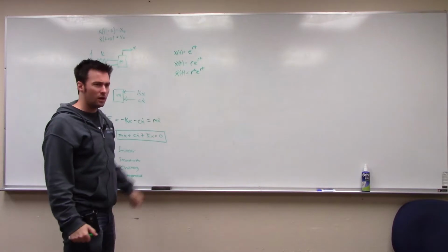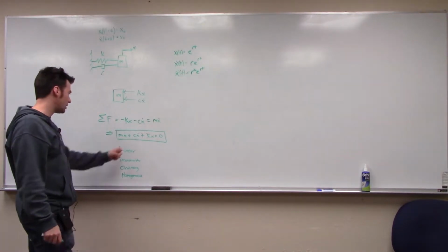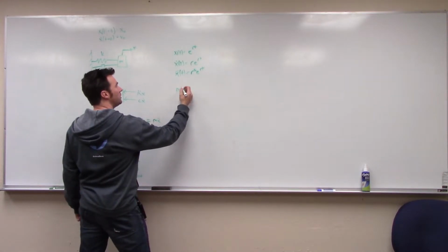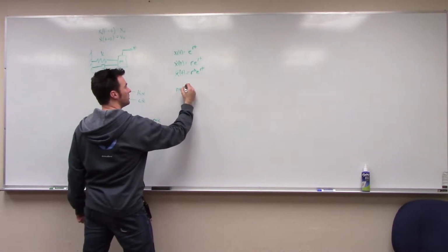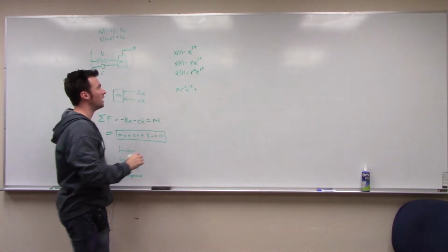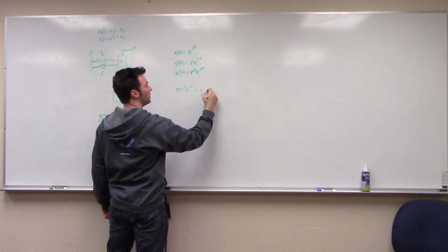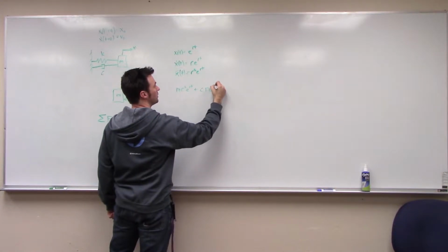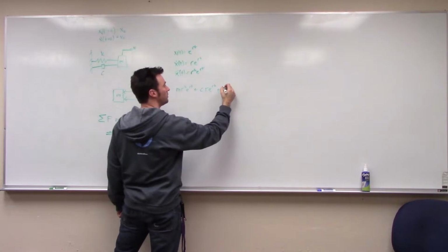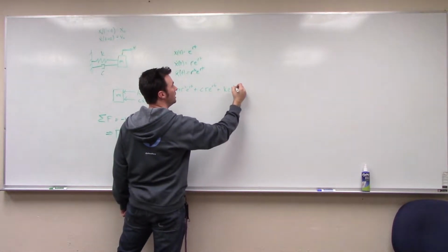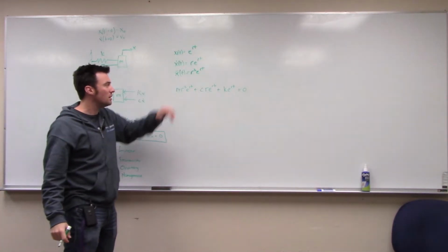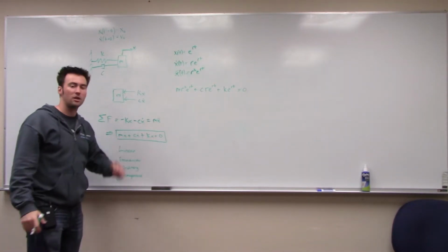All right, so we've got the three derivatives that we needed, and let's plug them in here. If we plug them in, we get m times r squared e to the rt, plus c times x dot, which is c times r e to the rt, plus k times x, which is k e to the rt, and that all still has to equal 0. If this is a solution, then when we plug it in, it still has to equal 0.